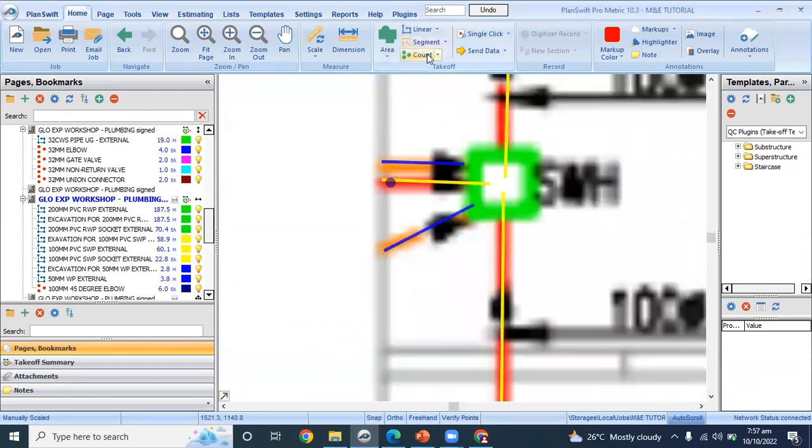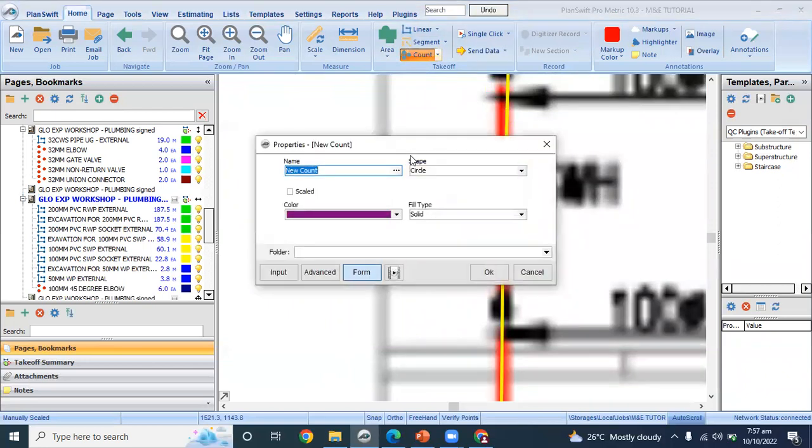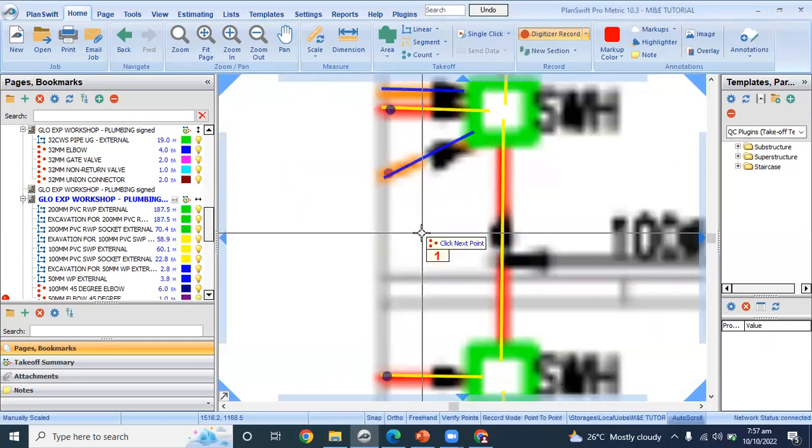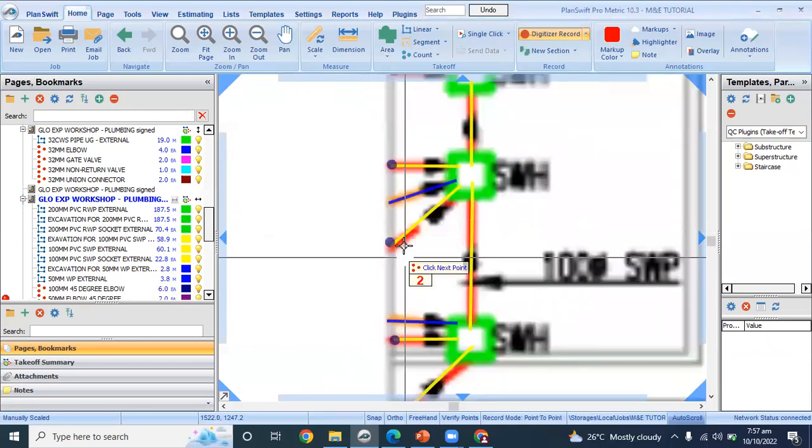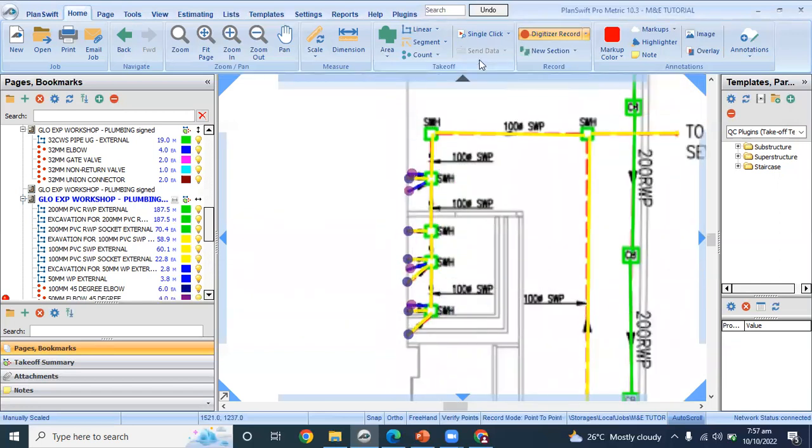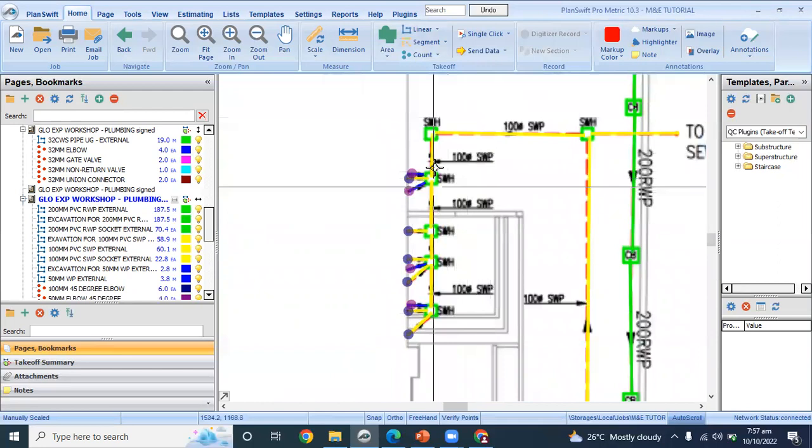What of the 50 mm 45-degree elbow? So 50 mm elbow, 45 degree. So mind you, whatever the size of the pipe is, that's going to be the size of their fittings, except they are reducing, or except a bigger pipe is connecting to a smaller pipe, then you are going to consider reducing fittings. So click OK. So we have one here, we have another one here, we have one here, we have one here. So that's that for the 45-degree elbow.